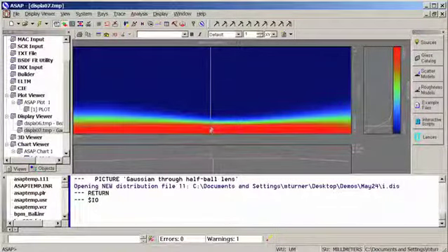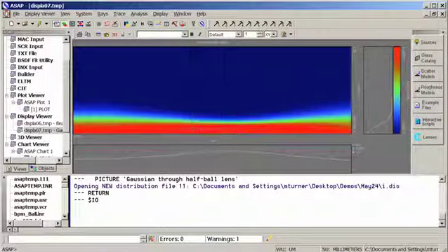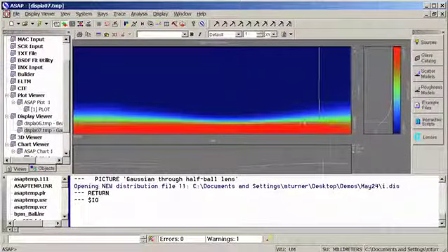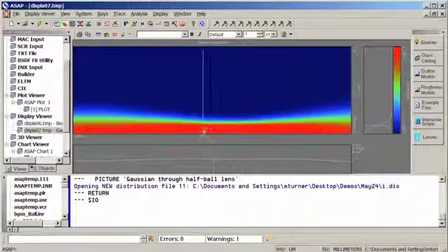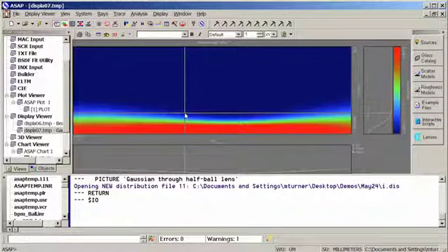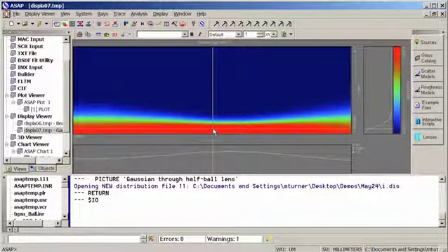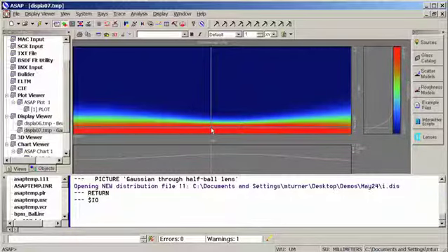We can use our cursor to get information about the size and intensity at any location within this system. But instead of simply propagating rays, ASAP is actually propagating through the scalar field of a Gaussian beam. This is necessary when you have small structures such as single-mode fibers, when you're doing fiber coupling efficiency calculations, and other optical structures that are small but large relative to the wavelength.